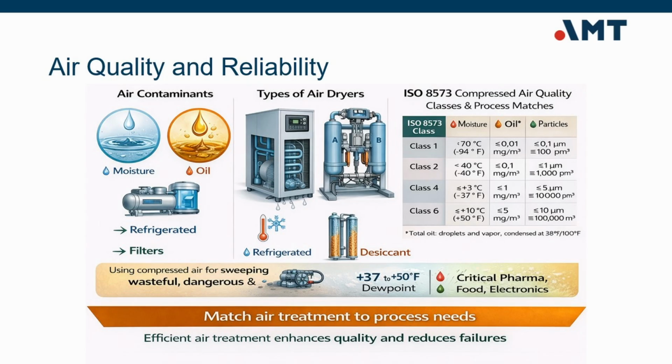Let's start with moisture. When compressed air cools, water condenses. If that moisture isn't removed, it can cause corrosion in piping, sticking valves, instrument failure, and in colder conditions, even freezing. In production environments, moisture can also damage product quality, especially in food, pharma, and electronic applications.